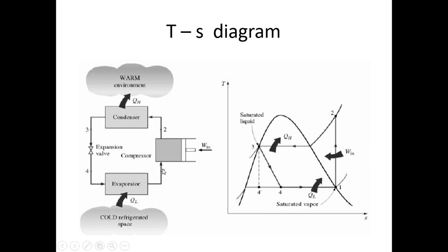So compressor 1, you have a saturated vapor entering into this compressor at lower pressure, that is suction pressure. This is a saturation point on this curve. So from here, compression 1-2 is an isentropic process, meaning entropy is constant. It's a constant entropy vertical line from the suction pressure to the delivery pressure. So 1-2 will be a vertical straight line like this. Then after 2, it's a superheated region.